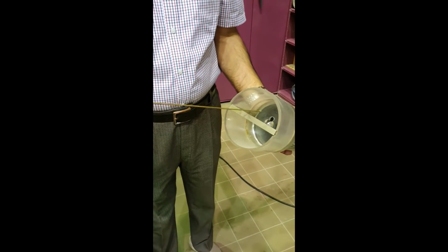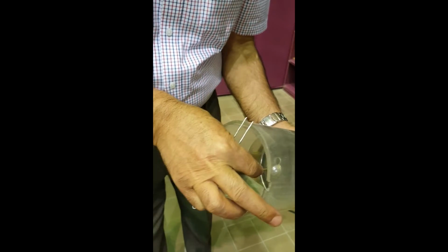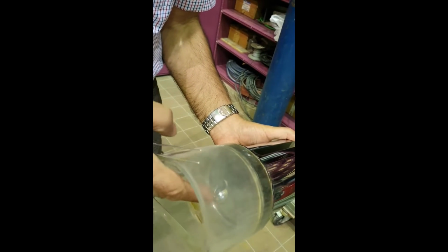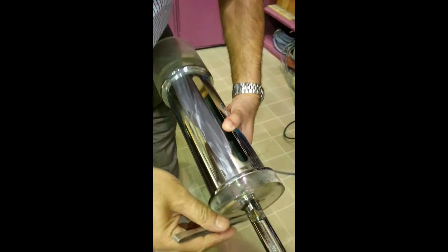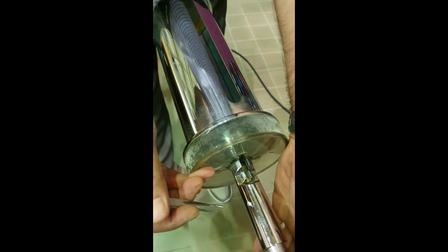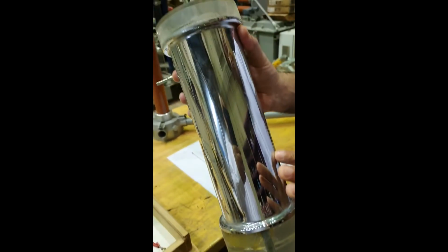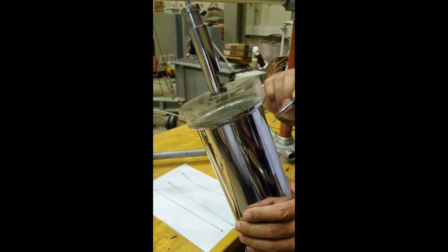For the solid conductor, insert it from the bottom side and let it sit there. Push it until it comes out from the other edge, then put it against your leg and push this down. There's a groove inside where it will sit perfectly. Just drop it down and this is fixed. This will be at high voltage, and this outer cylinder will be grounded. So we have put the 1.98 solid conductor inside and the outside will be grounded.